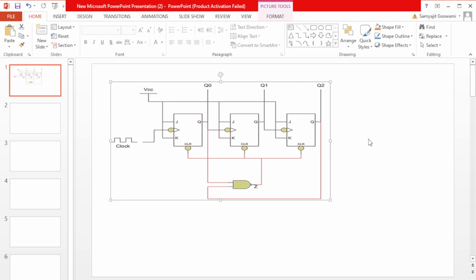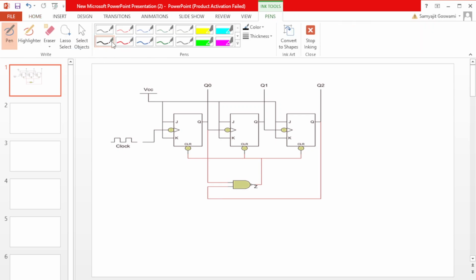For this purpose you have to know, first of all, that in the case of mod n, n stands for the number of steps. Okay, here I am designing the mod 5 counter. So how many steps do we have to count? That means 5.